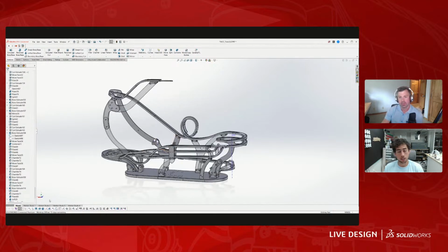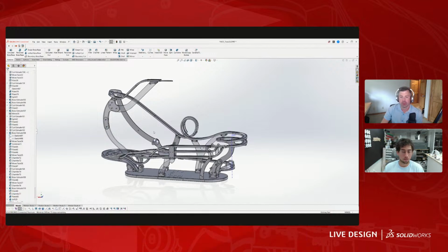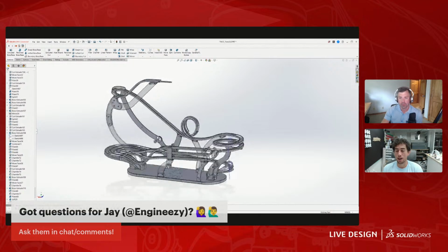And that being said, you can do the mechanical sketching in just a sketch as well. And I do that often, but sometimes you have to constrain everything. And if I'm just trying to get a really quick, unconstrained model, Motion Gen's really good for that. But honestly, before that, I always just use SolidWorks to do this stuff as well. Okay. So just a 2D mechanism sketch using the regular 2D sketching. Yeah, the layout sketching, yeah. Which works really well also, and it's very quick and easy to do. And the one advantage of that over Motion Gen is you can use dimensions. Motion Gen isn't really parametric, so it's very basic.